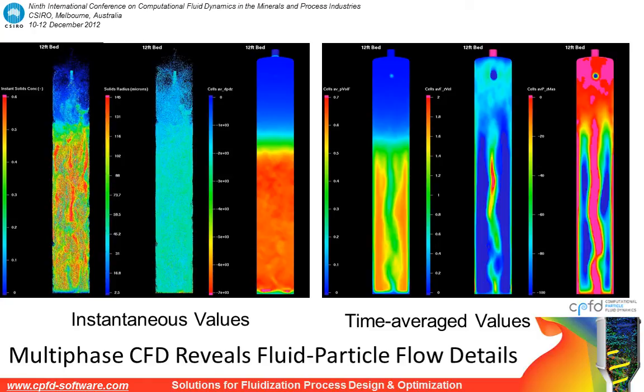You can see on the far right, where we're looking at the average vertical velocity, that over most of the cross-section of the bed, the particles are moving downward slowly. And in the center of the bed, and in some cases along the walls, the particles are moving upward, but comparatively quickly compared with the downward particle flow in this annulus around the vessel.